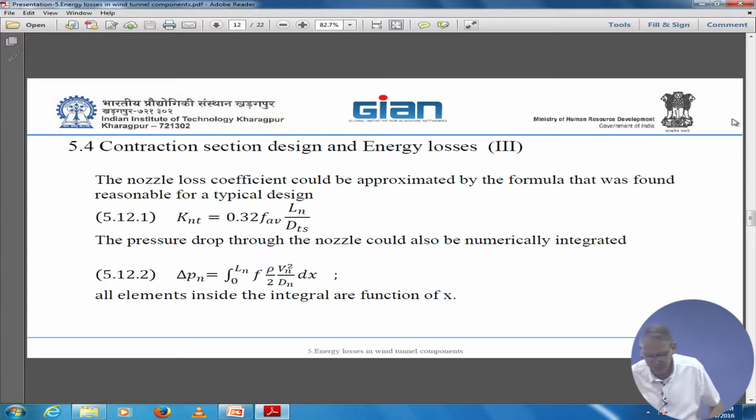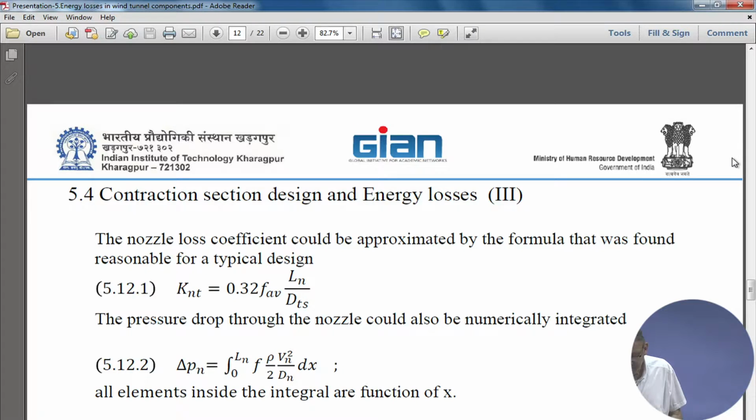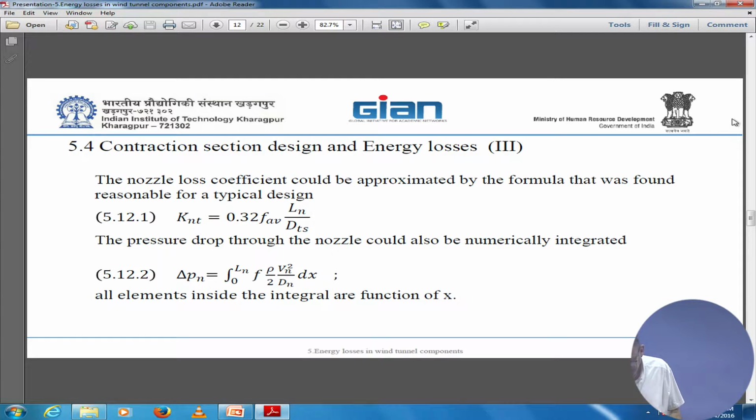Porosity is 1 minus the diameter of the wire divided by the distance between wires, to the power of 2, and 1 minus that gives you the solidity. And the Reynolds number of the wire is simply the velocity across the mesh times the diameter of the wire.